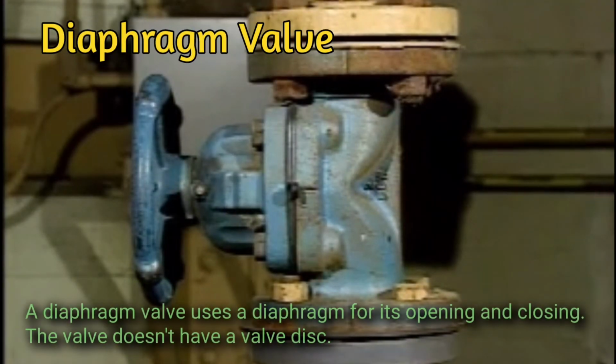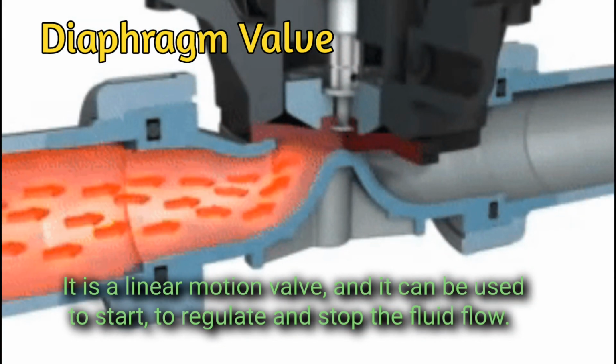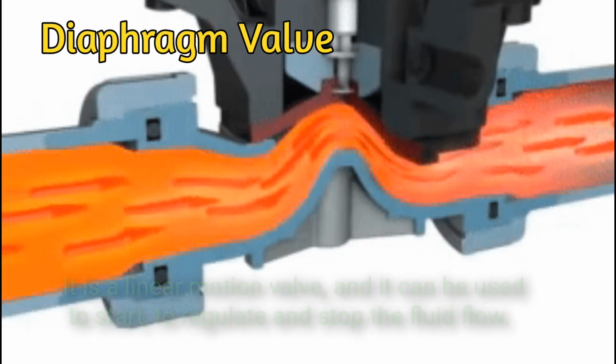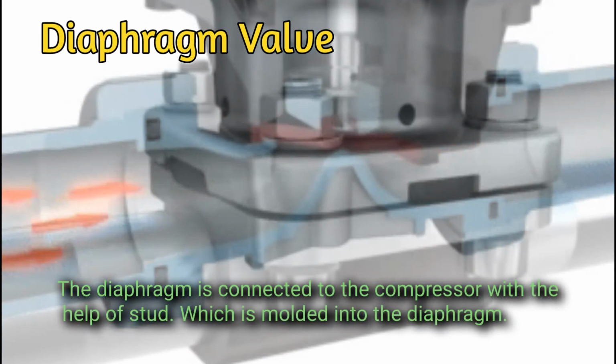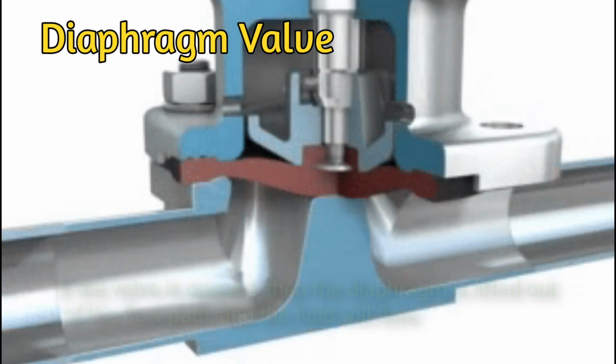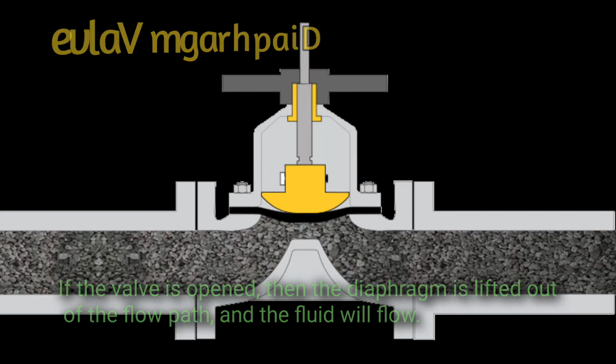Diaphragm valve. A diaphragm valve uses a diaphragm for its opening and closing. The valve doesn't have a valve disc. It is a linear motion valve, and it can be used to start, regulate, and stop the fluid flow. The diaphragm is connected to the compressor with the help of a stud, which is molded into the diaphragm. If the valve is opened, then the diaphragm is lifted out of the flow path and the fluid will flow.